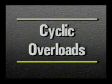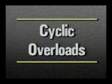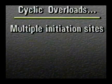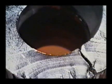If careful examination of a fatigue initiation site shows no evidence of abnormal stress raisers, we should next look for road signs of cyclic overload. Indications of cyclic overload are multiple initiation sites, large final fracture, and low cycle fatigue. Cyclic overloads often start several fatigue cracks at the same time. The fracture often connects ratchet marks as an indication of excessive cyclic loading.